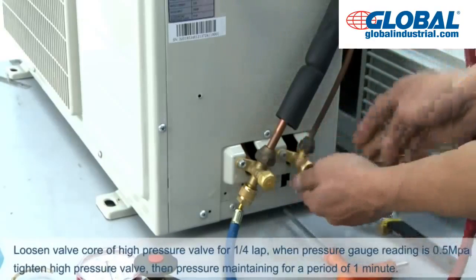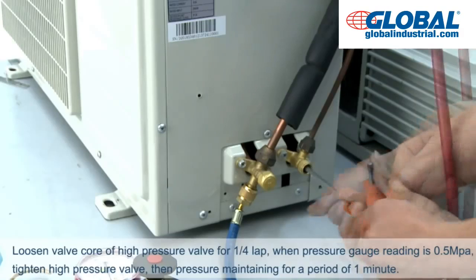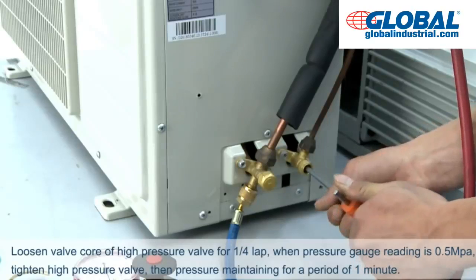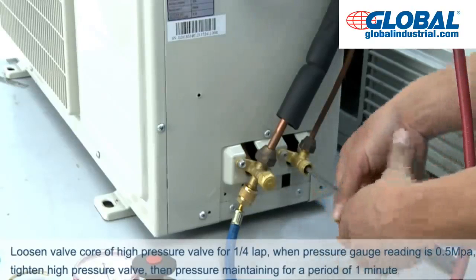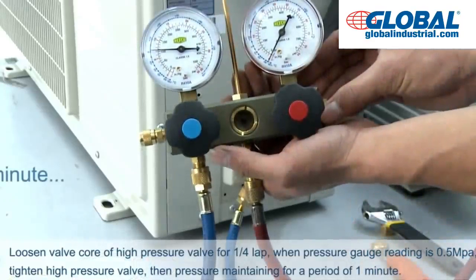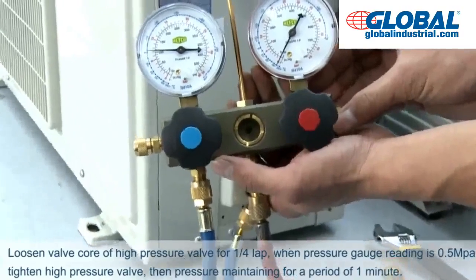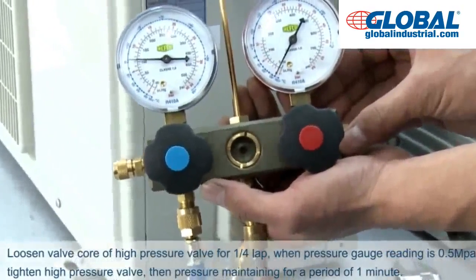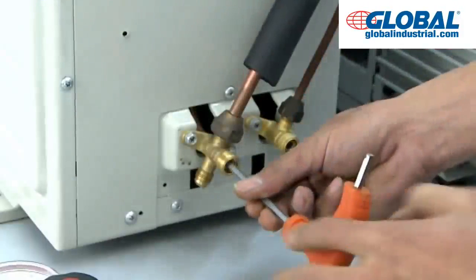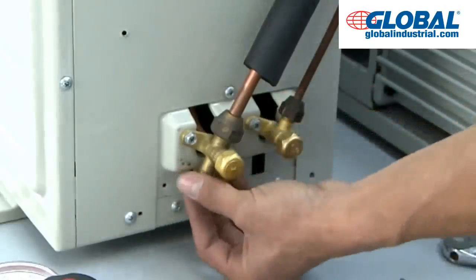Unscrew valve cap of high pressure valve and low pressure valve, and loosen valve core of high pressure valve through turning it for 1/4 lap counterclockwise with hexagonal socket for 5 seconds. Generally, turn off valve core if pressure gauge reading is about 0.5 MPa. Wait 1 minute. Check the indicating of pressure gauge. There should be no change. Open fully valve cores of high pressure valve and low pressure valve. Tighten valve cap.